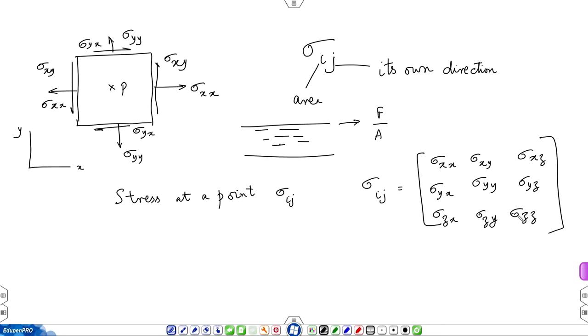Okay. For example, there is a cylinder rotating and then an outer cylinder fixed. So, the gap, if it is uniform, then the velocity distribution will not change from one angle to another. So, the flow field is axisymmetric. So, there is no dependence on theta. Suppose it is very long, then there is no change happening from one z location to another. So, it is independent of z. So, this 3D example, real life example becomes just 1D in the radial coordinate.